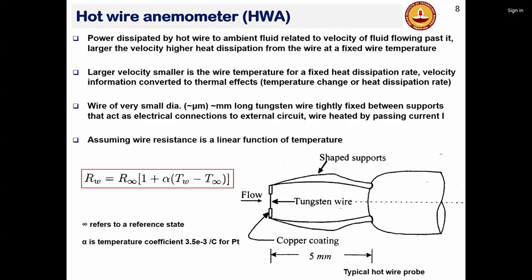If you are trying to maintain a constant temperature, since the heat energy is coming into the wire, you have to reduce the resistance of this circuit. Basically, the control becomes the reverse compared to a situation where the ambient is cooler and the wire is hotter.